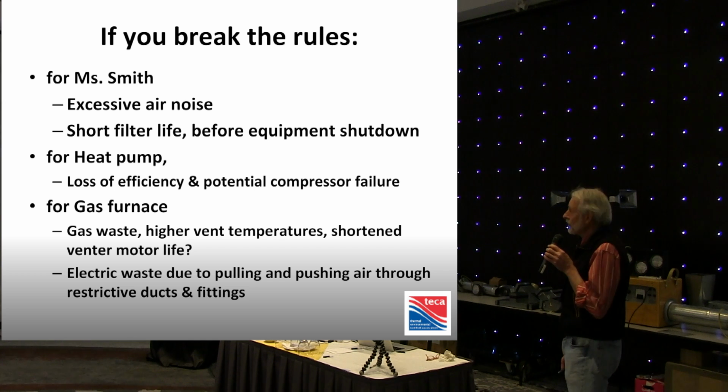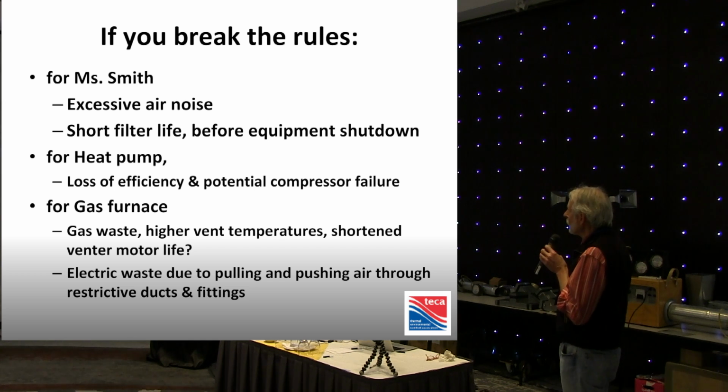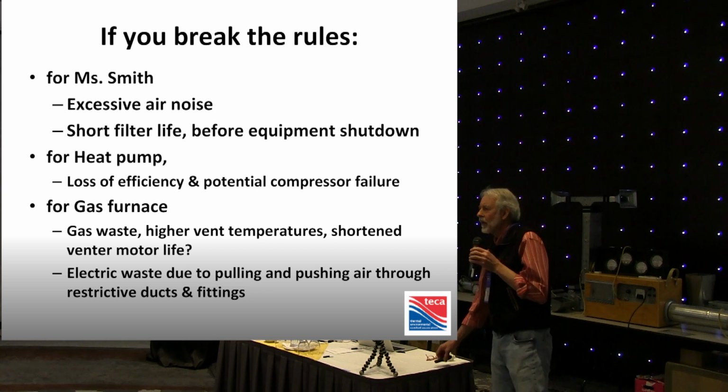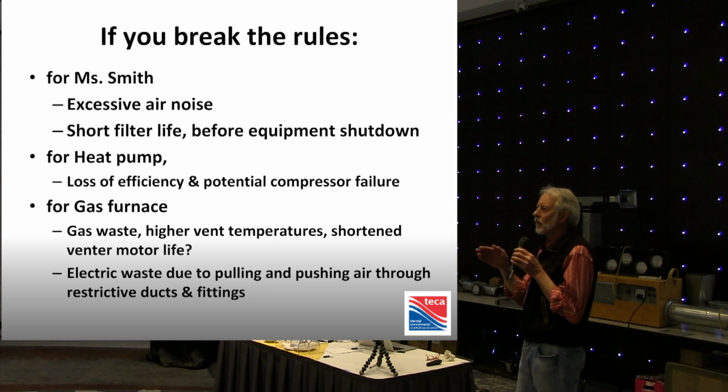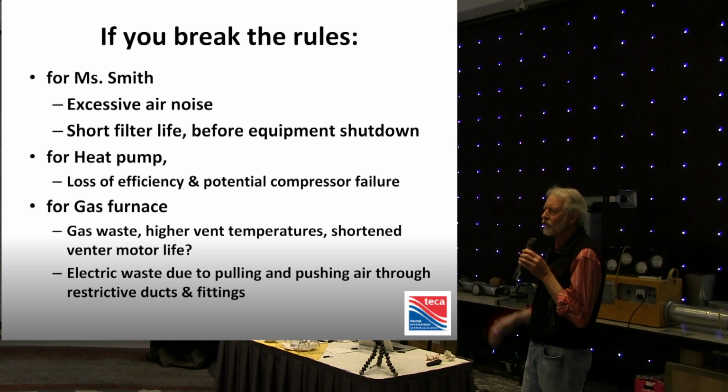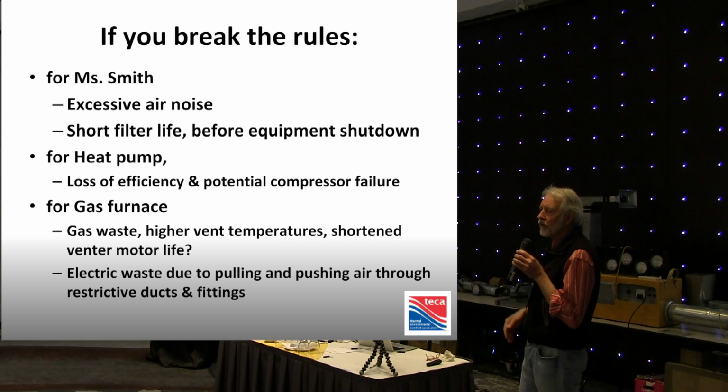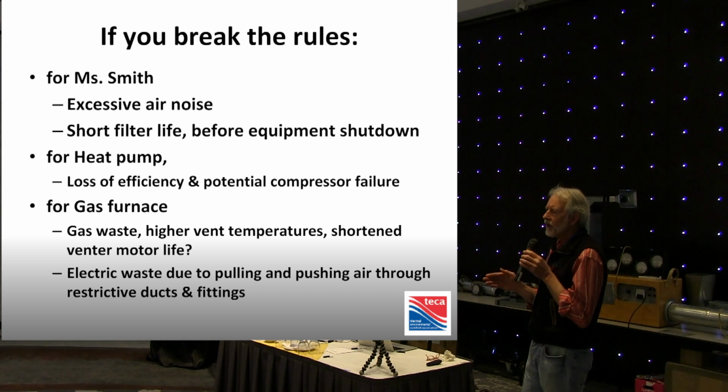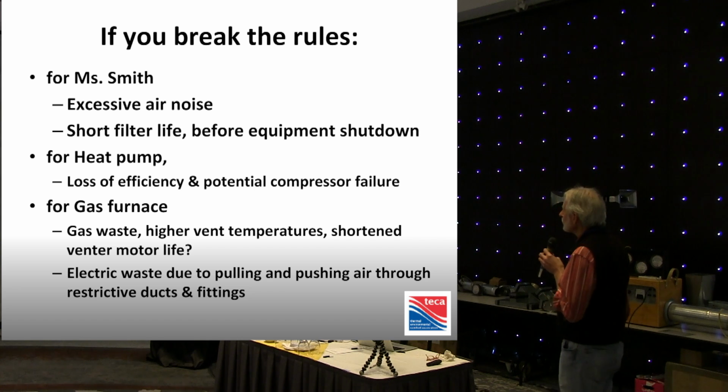If we break the rules, we get excessive noise, and we get short filter life. It's not commonly understood, but if your system is put in a marginal configuration so that the furnace is just able to meet the requirements for moving air through it, and you put a filter in, that's bad enough. But that filter may have a very, very short life. The filter is still fine, but it's pushed the system over the edge to where you're now starving that equipment. So your filter life will be very short if you have a restricted ductwork system, and the filter just becomes an added piece of straw on the camel's back to actually break the camel.